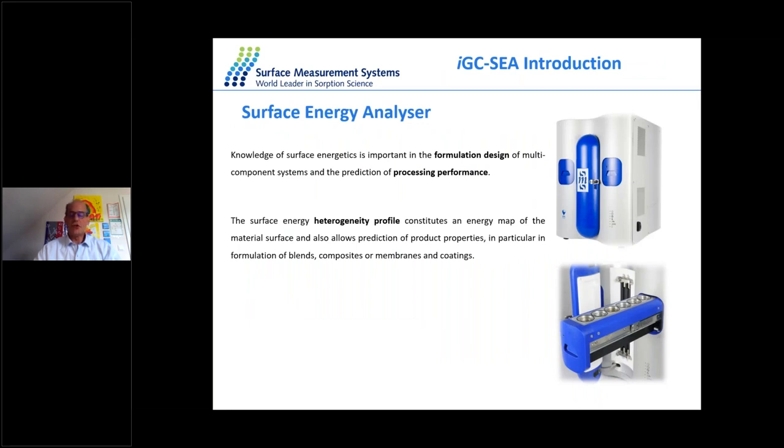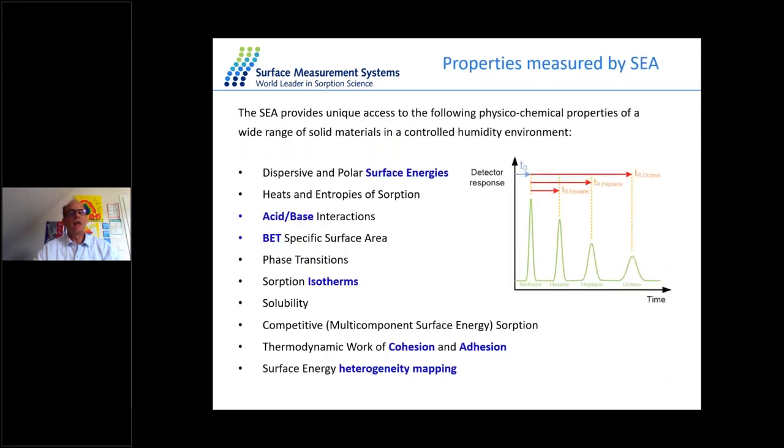So here you see the surface energy analyzer. It is an IGC, or inverse gas chromatograph. What you see on the right side is the instrument. In the middle, you have an oven where you place your samples, and you put different liquids and organic molecules in the reservoirs, and also water and organic molecules. What you're looking at is the retention time.